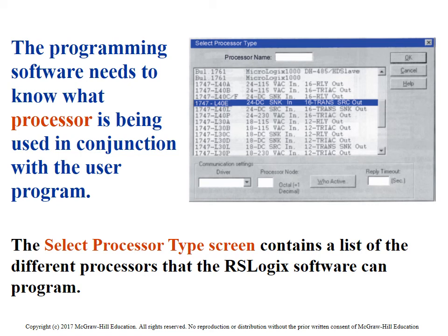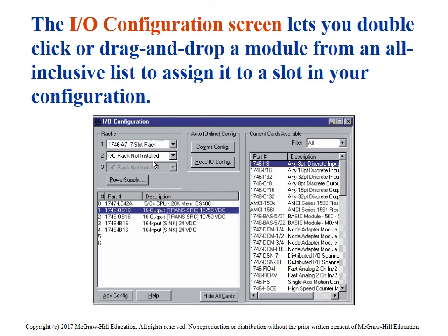So, for instance, you've got to make sure you select the right CPU, the right number of inputs, the right number of outputs, the right cards that are in those slots. It can be time consuming, but it's not so bad. We'll get through all that in lab.